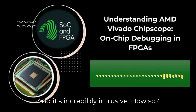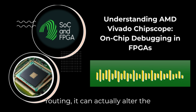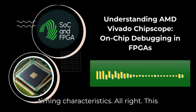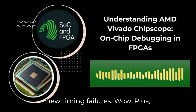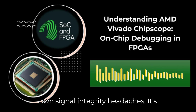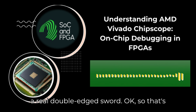And it's incredibly intrusive. How so? Well, adding all that extra debug routing can actually alter the physical implementation. It changes timing characteristics. This observer effect can genuinely mask the bug you're hunting for, or worse, create new timing failures. Plus, external probing itself can introduce its own signal integrity headaches. It's a real double-edged sword. Okay, so that's out. What else?